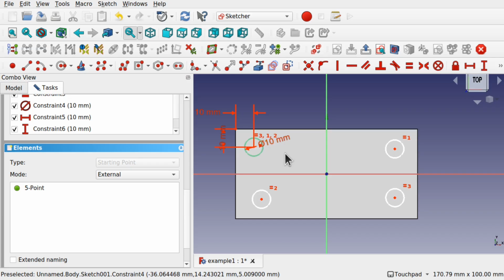This one is fully constrained, but the others aren't. So we've got constrained geometry, but unconstrained geometry around the outside. Let's start constraining these geometries now. So I want to select this point and keep them in line. So this keeps in line with this one. We could go through and select this point and pull in geometry from our external source, our external pad, and do the same, but it ends up getting messy.